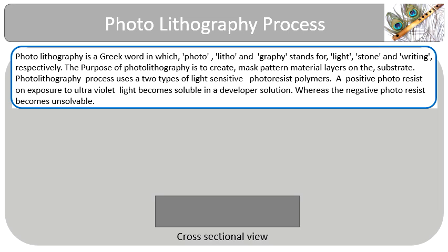The wafer is developed to dissolve exposed or unexposed resist areas. Etching transfers the revealed pattern into the underlying layer. Remaining photoresist is stripped off after etching. This process is repeated for different material layers of the VLSI structure.